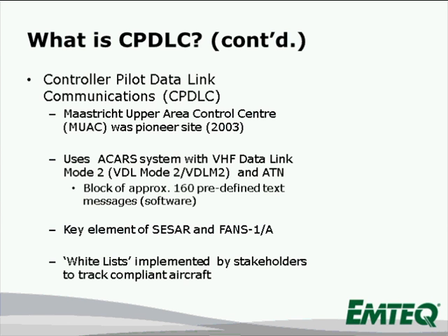CPDLC is a key element of the Eurocontrol EASA STC, as well as the FANS 1A, the Airbus and Boeing developments for the future air navigation systems. And they use a means of whitelist to track which aircraft are compliant to the airspace. In Europe currently, there's several whitelists that have been developed for aircraft that meet the current FANS and CPDLC requirements so that controllers know which aircraft are aptly equipped and can benefit from using the CPDLC operation.